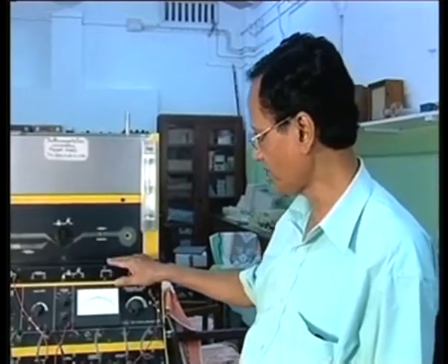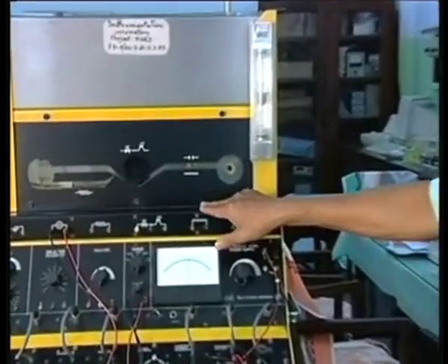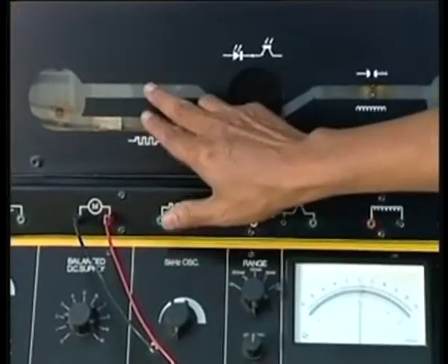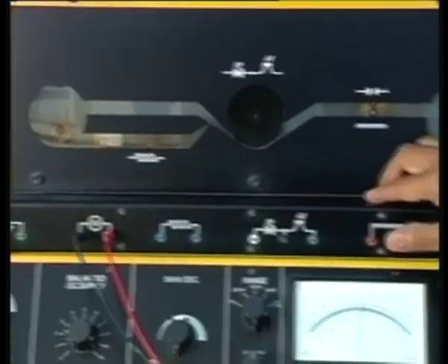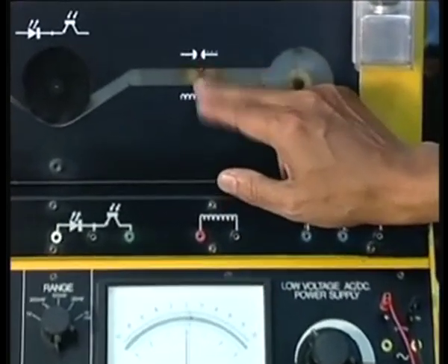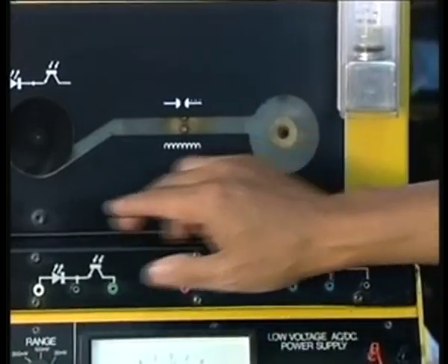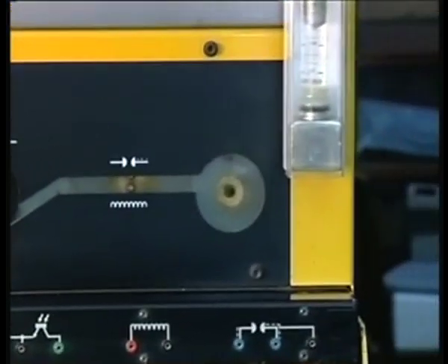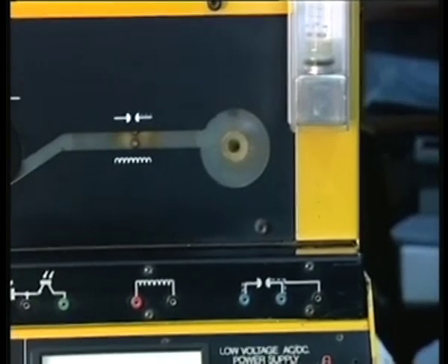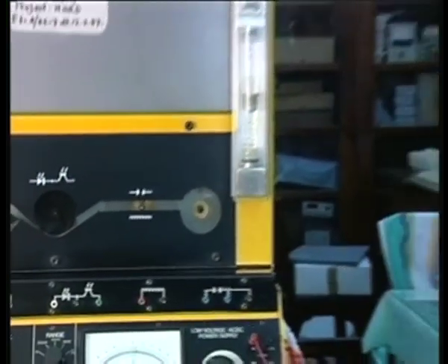Similarly, the hot wire anemometer also has electrical output, and this is the hot wire anemometer. We cannot see it from here because it is inside. And the magnetic flow meters also have electrical output. So all these flow meters except this rotameter have electrical output. Now, electrical output has advantages. If you have an instrumentation system, you can directly convert that signal to the current domain, 4 to 20 milliampere, then you can digitize it if necessary.